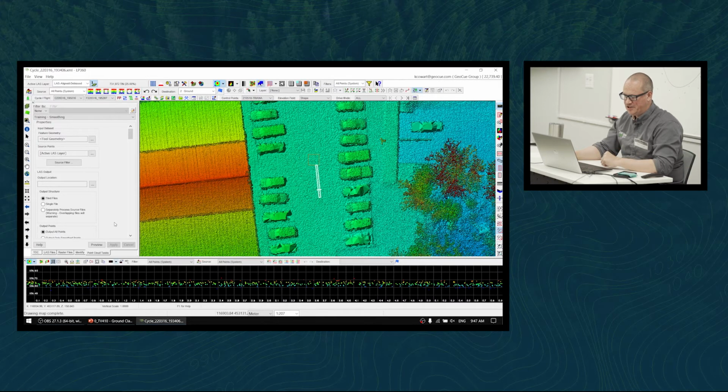And we're not really going to change anything on this. You should always leave the tiled files option checked. You always want tiled files. We're not going to mess with any input on this. We're really just concerned with the output. This is another destructive edit because it's going to compress noisy portions of our point cloud and permanently alter it. So let's hit this ellipsis right here.